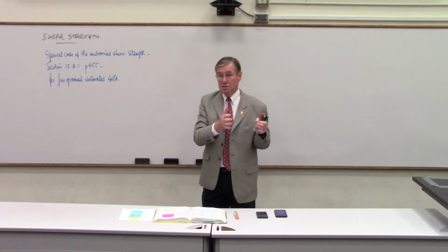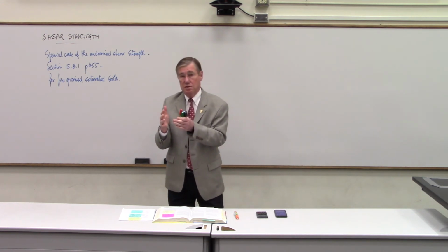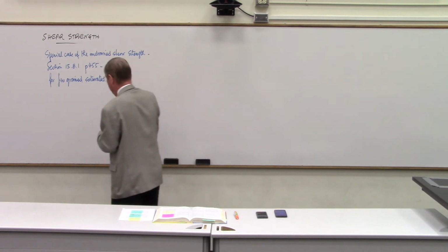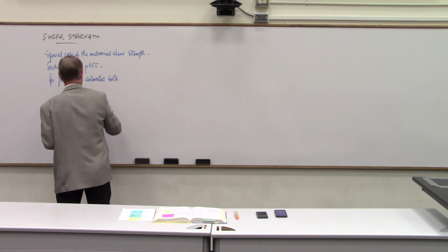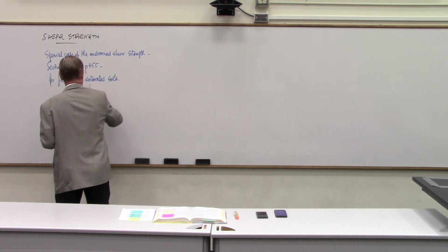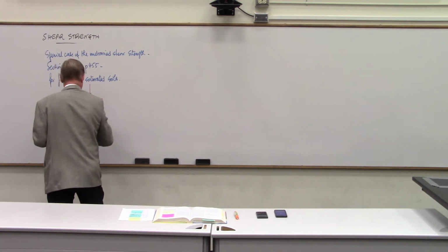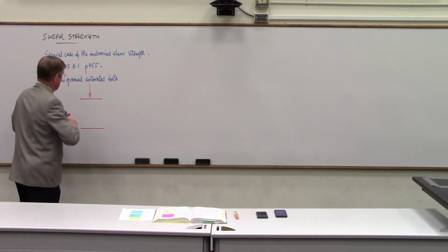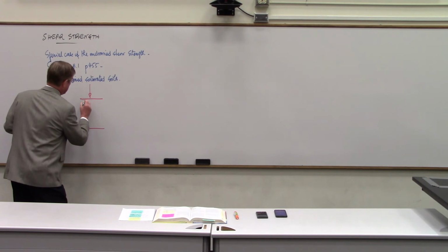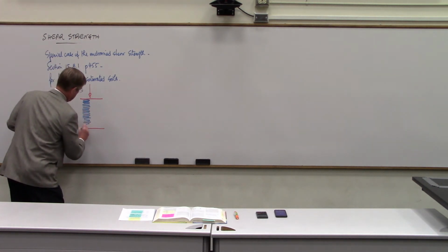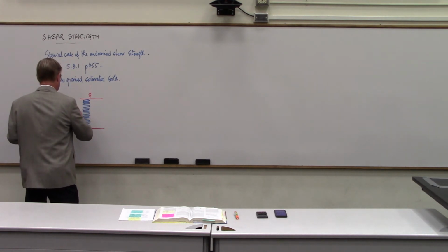You have the skeleton that has a certain stiffness, and you have the water that also has a certain stiffness. And in the undrained behavior, if you think of trying to compress by applying a load, the two springs, so here you have a stiff blue spring like this, which is the water.